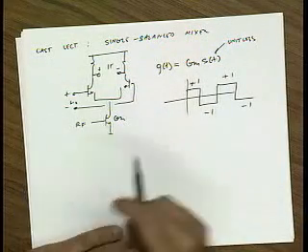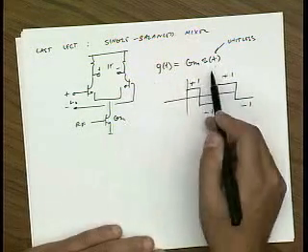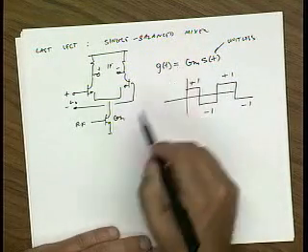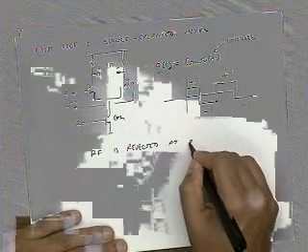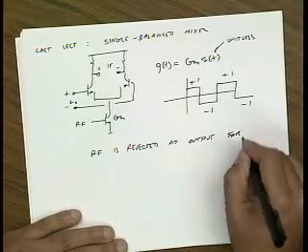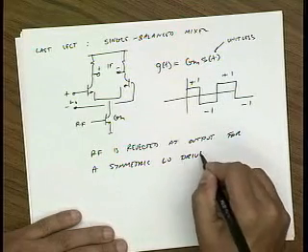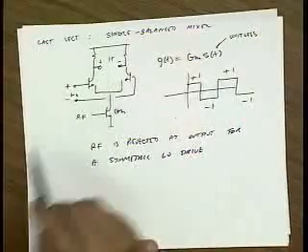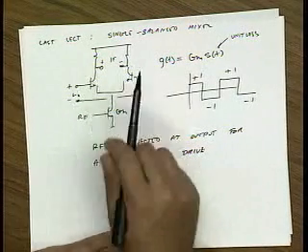Okay? So the nice thing now is that because this G of t doesn't have any DC value, when we multiply our RF by this G of t, there is no RF at the output. The RF is rejected, for a symmetric LO drive. Okay. So as long as we can maintain this balance, we assume that this is a fully balanced circuit, we reject our RF. Okay? But we still have the LO leakage to the output.